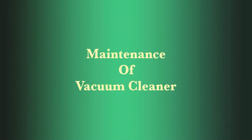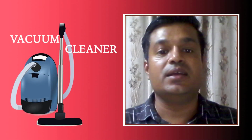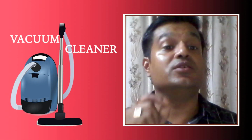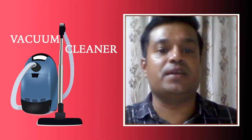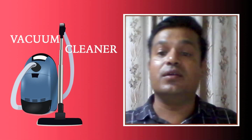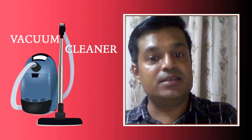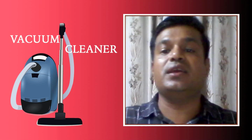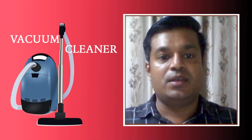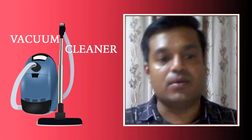Next is the maintenance of the vacuum cleaner. Regular maintenance is essential to ensure the vacuum cleaner's efficiency and longevity, and also effectiveness in the cleaning. This includes emptying or replacing dust containers or the bags, cleaning filters, and periodically inspecting and maintaining the brush roll and other components. Here I am going to give a comprehensive guide to maintaining your vacuum cleaner.